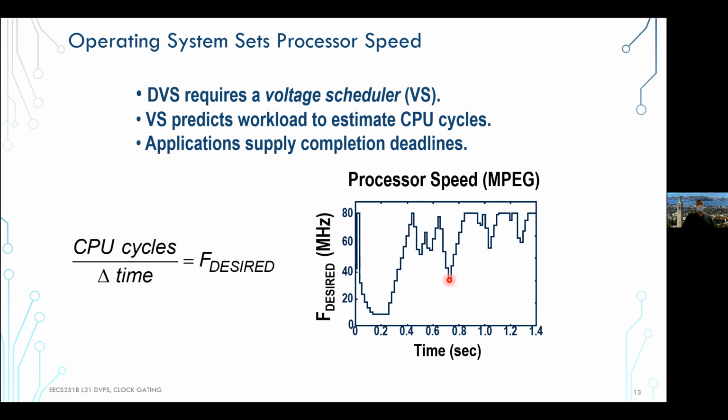And of course, how granular are these adjustments? That depends on the voltage regulators that you have and are trying to use. We'll see later, there've been examples of just dithering between two states, because it's very easy if you do switch cap ratioed converters. They're very efficient, but they can only give you a few discrete supply levels. The question is, is that enough, or do you really need to ride the continuous curve? Maybe you don't. In many other things, we've seen that coarser piecewise approximations give you basically 90+% of an answer. So why bother with that diminishing returns fraction, because you're significantly increasing the complexity of your voltage scheduler or the regulator, things like that.